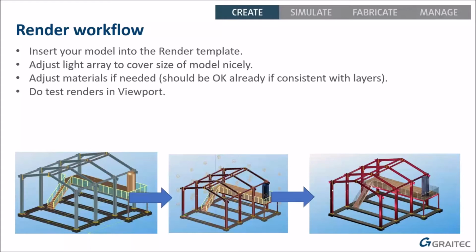It'll probably render the whole screen in about a minute. If you waited for it, it will get to full quality in a minute or so. Once you're happy though, and you've said, yeah, I'm happy with the quality of the render and the settings I've got, you then change the setting from render in viewport. You say render in window. And then you click the render button, and it'll open another window and create all the rendering in there.